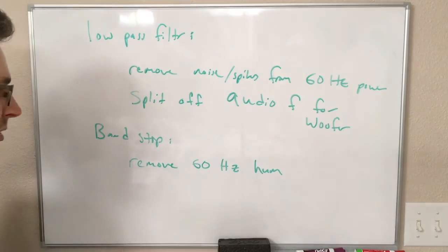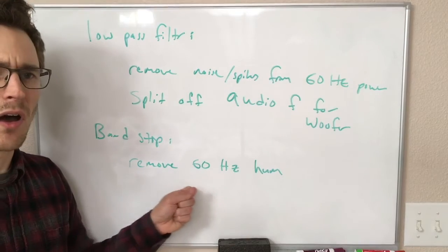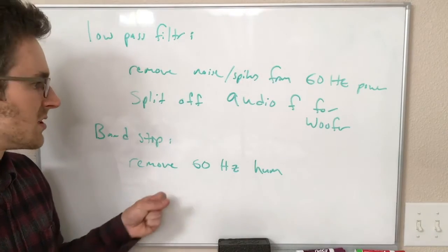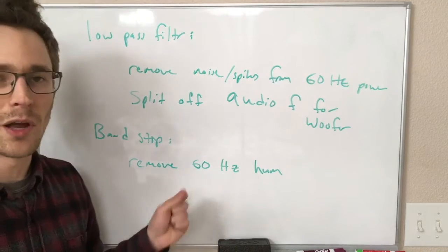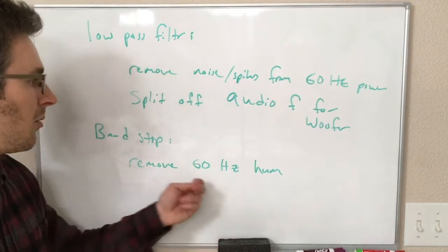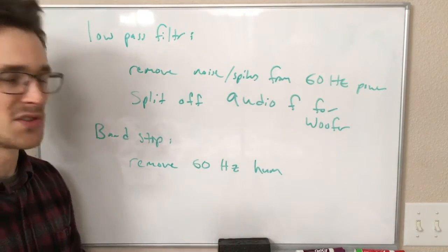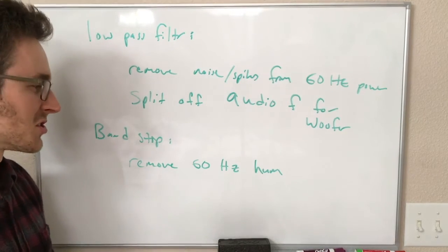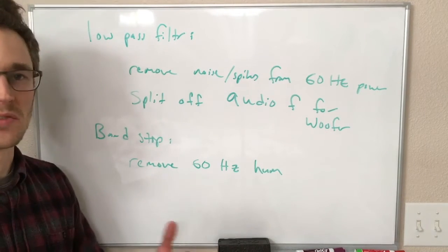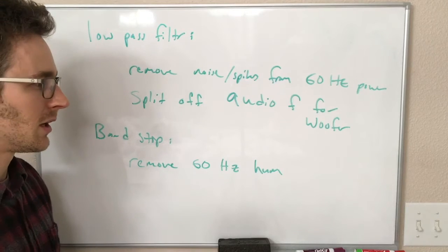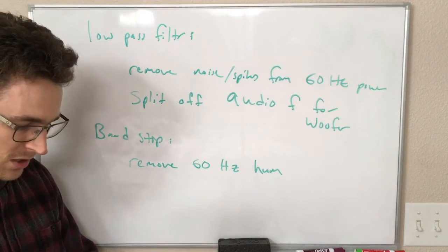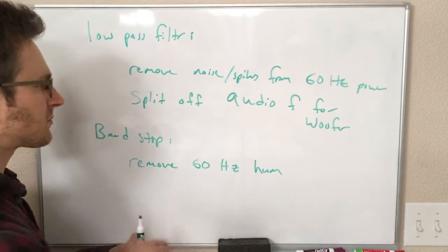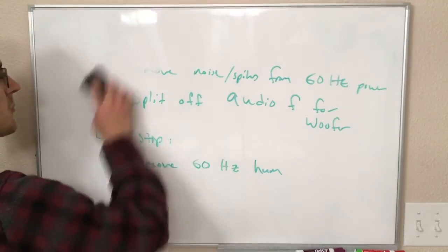So that's super useful. You'll also see stuff like this in audio. A 60 hertz or 120 hertz filter in stereo amplifiers is really common because hum at that frequency is a similar problem to what I just described: it's some sensitive signal that you're amplifying really big, and that can be affected by the 60 hertz wall voltage. So yeah, these are a few applications we have.